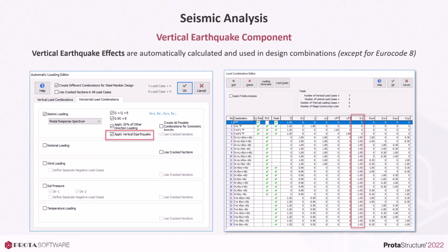For some cases, codes require a vertical model analysis to take the vertical component into consideration by the help of a vertical acceleration spectrum. This methodology requires a careful identification of vertical masses and detection of necessary vertical local modes.